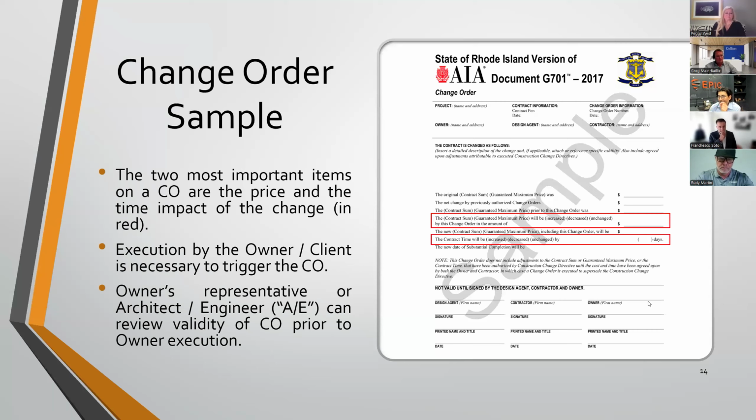But when it's an active change order, that means that all three parties here have signed it. The last and most important party is going to be the owner. That makes it executed. So the designer confirms for validity and makes sure that it is an active one. Contractor obviously submitting it, that would be the first signature. And then to make it active, the owner saying, okay, let's go ahead.